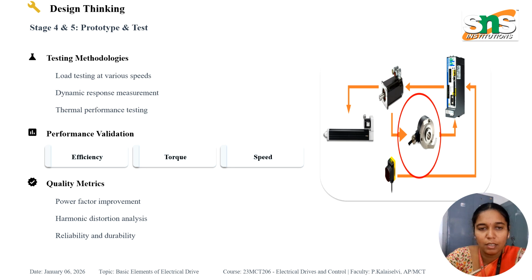And then the final stage is prototype and testing. In this we verify performance using the load test, dynamic response test and thermal testing. We evaluate quality using efficiency, torque and speed accuracy, power factor improvement, harmonic distortion and reliability.